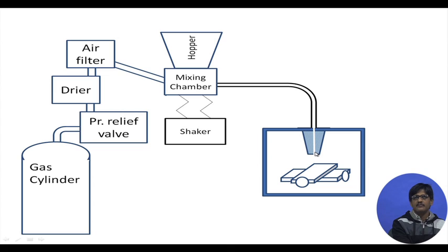Why is it small in diameter? That is because if the diameter is small, the jet of abrasives emanating from the nozzle will have a jet diameter limited to say 0.3 to 0.9 millimeters, and therefore it will be able to give rise to a very narrow cut or groove or diameter of drill, like that.